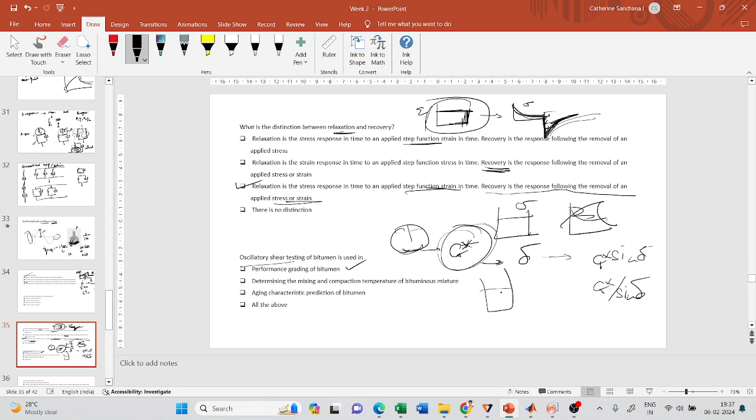But in some cases, we also use a dynamic shear rheometer and test using a parallel plate system, where we find out the delta, where it approaches 90 degrees. Why should it approach 90 degrees? Because at 90 degrees, the material is expected to show a viscous response.